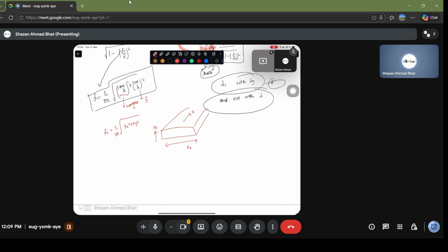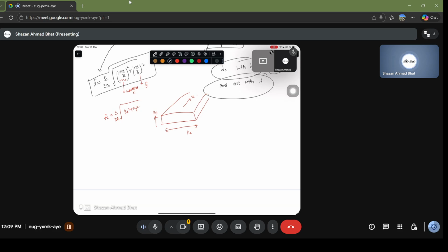It's difficult to show it like this because of the three-dimensional spatial spread of this particular electromagnetic wave. Essentially, if you look from the top end of the waveguide at the first dominant TE mode, you're going to see something like a Gaussian, where this is kx and this is ky, and this packet is moving all together in the z direction.